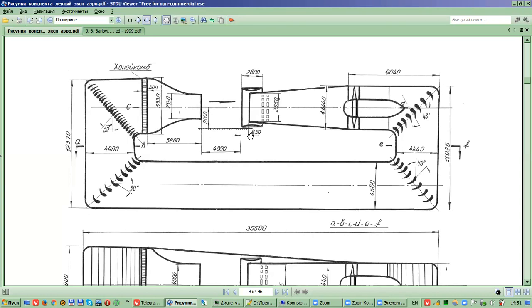So you have a lot of work inside test sections between runs of the wind tunnel. And if you have an open test section, it is a simplification of work. In closed test sections, you need to open a door, maybe extract the model from the wind tunnel, and this is a lot of time. With open test sections, it is very simple, but open test sections are very